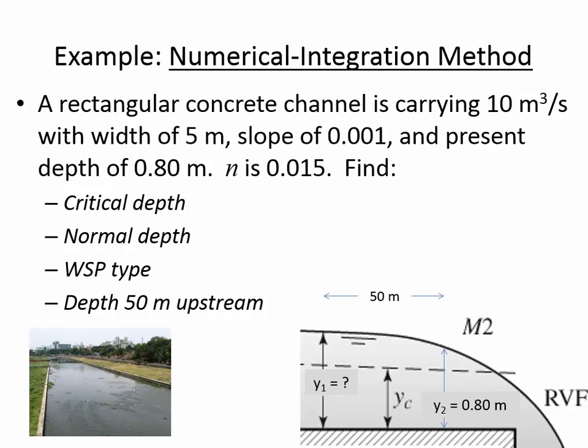And then the fact that the given flow depth at this location of interest is between normal and critical puts it in zone 2. So this is an M2 profile. And what M2 means is that it's getting shallower downstream and deeper upstream.